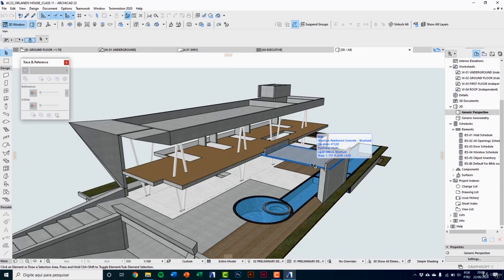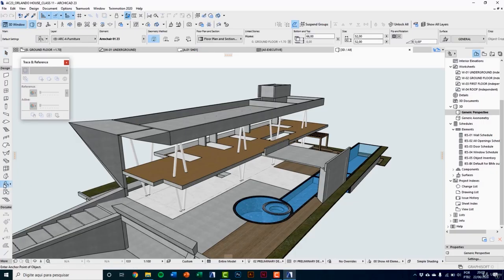So basically in this class, I'm going to teach how to design structures in 4 different ways from the conventional way we have learned using tools such as columns, beams, slabs, and walls. The 4 ways are the following: using Archicad library, importing standard steel profile, complex profile, structure of variable sections. Starting by Archicad library, go to Object Tool, it's this chair icon.